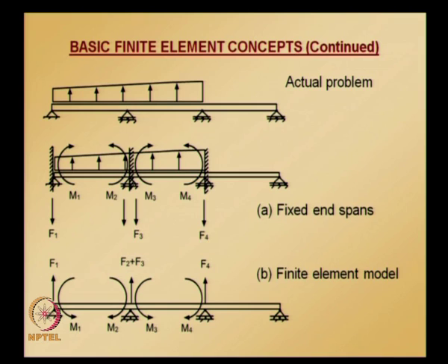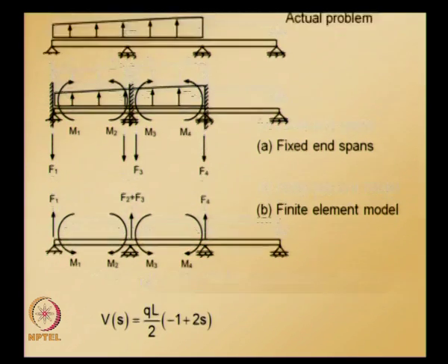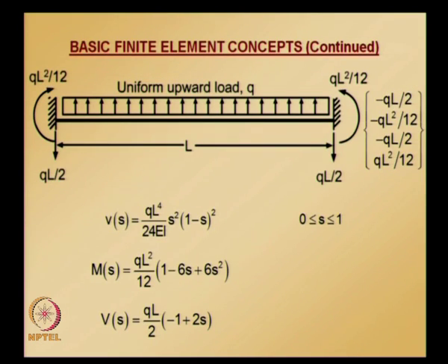So, in each particular span the moments and shears we can get from the fixed end solutions that are already documented in most of the mechanics of material books. So now, for example, if we take a fixed end beam subjected to uniform upward load, the displacement, bending moment and shear at any point along the span are given by these formulas,